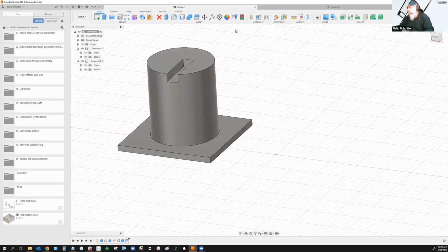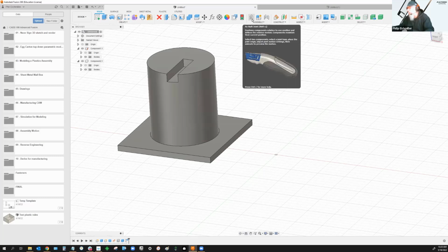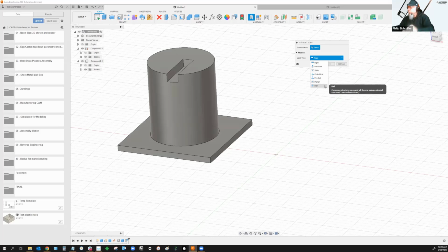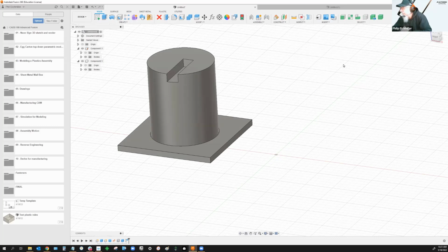And if I wanted to use a joint, right now I could use what's called an as-built joint, and that lets you take components that are already relative to each other and define the motion or lack of motion between them. So it's another extension of that joint. That's kind of why I said that we had improved upon Inventor just a little bit. Sean, I think Inventor would super benefit from getting an as-built joint in there, because you can do multi-body to assembly workflows in Inventor, and as-built joints would just be perfect for that. Anyway, does that help at all, Space?